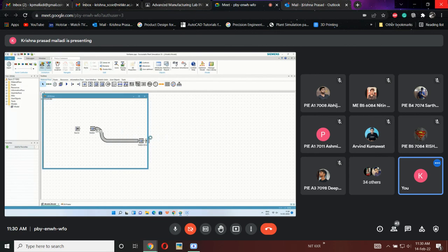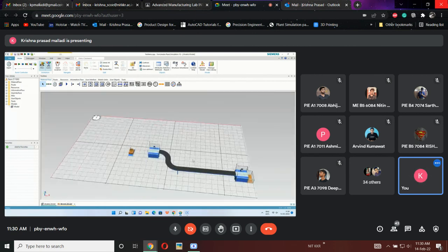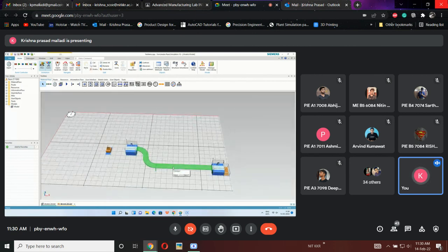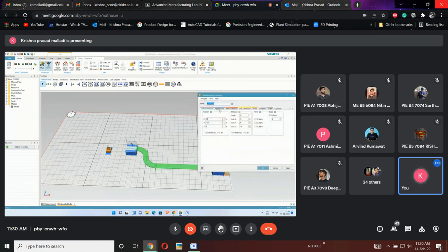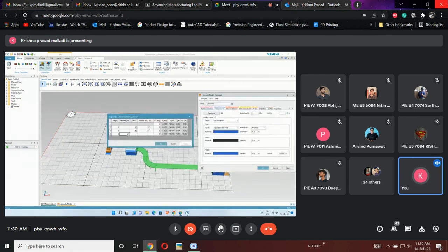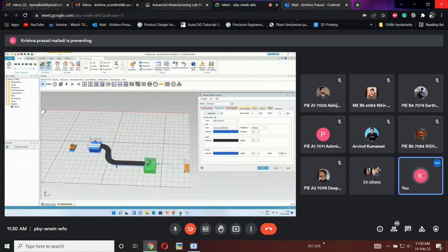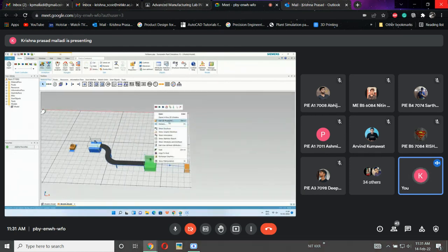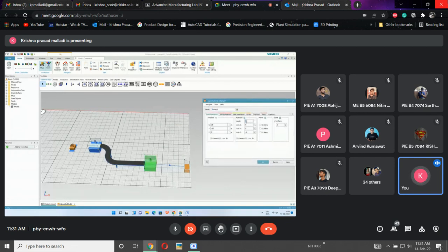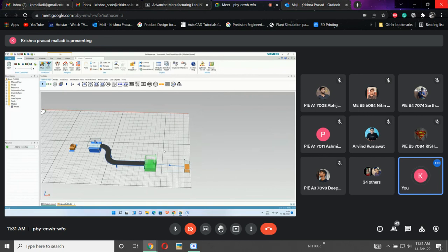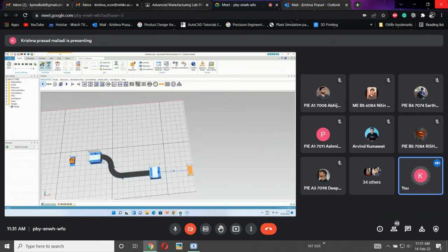Yes. Now it was defined into 3D. You can do any type of modification here. Here I am pressing M and I am entering into edit 3D properties. I can change the appearance. I can change the segments. Here it is 10. I don't want 10 as the length of this one. I want 5. Okay, I have done the modification 5 and I want to change this orientation also. I am changing it in 3D properties and here I am changing it to 90 degrees. Okay, so I have changed its representation.